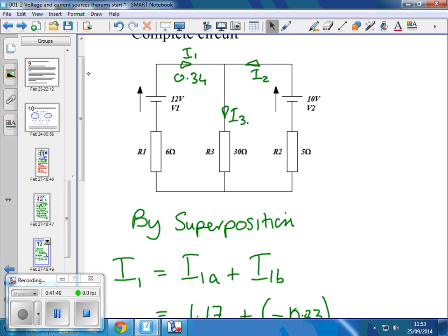It says the battery's completely discharged. It isn't actually completely discharged, but it's not going to provide what you need to run that circuit. But one way to think of it, in terms of this model, is that the internal resistance of that battery, as it discharges, is increasing. That's the way we could model that, and it is only a model.